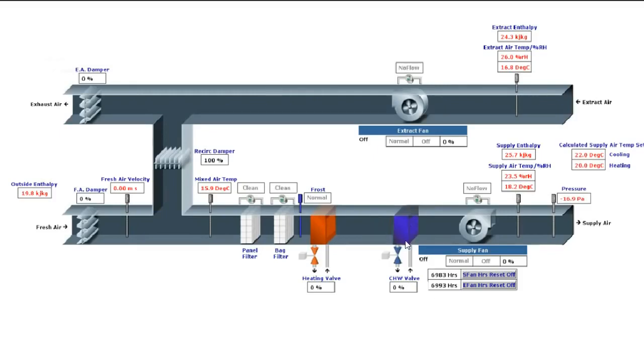coil, and you can cool the air down here or change the humidity using this one. And then that's being sucked obviously by the fan and being pushed off. Here you can see that it's measuring the supply air relative humidity. So we've got some measurements here for the temperature and also the humidity, and it's also measuring the enthalpy here. So this is a more advanced control system, which we won't talk about so much in this video.